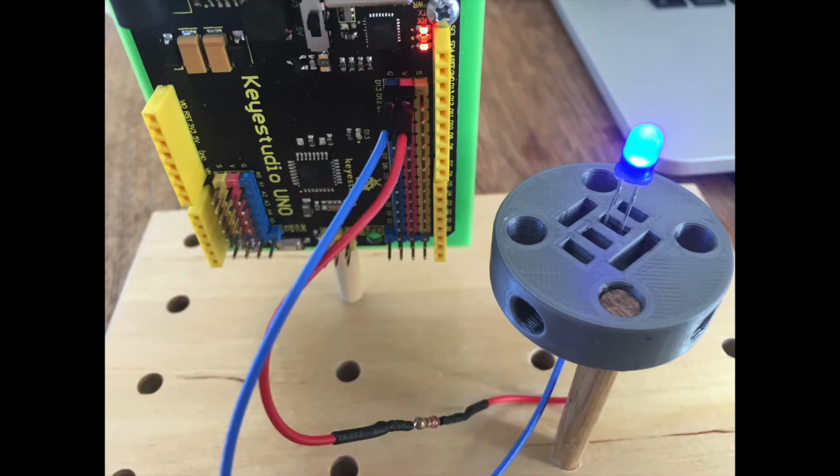Now that we have created our conductive pathway connecting the power through a resistor to reduce the voltage to our load, which in this case is an LED, and then back to ground, we have made a complete circuit. Now connect the USB to the microcontroller and your computer. If your light comes on, you have done it correctly.